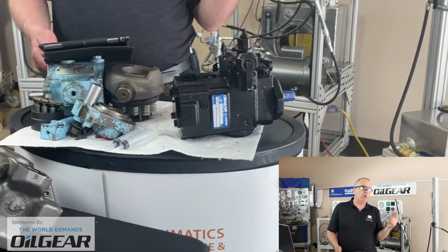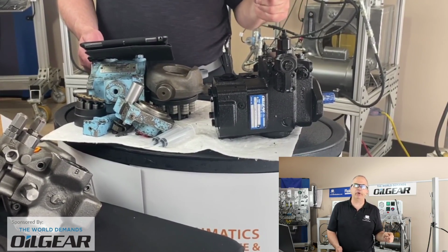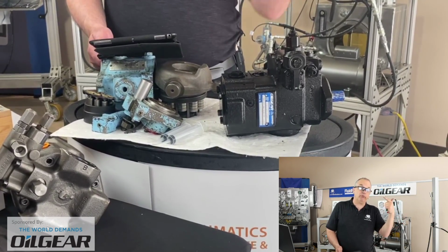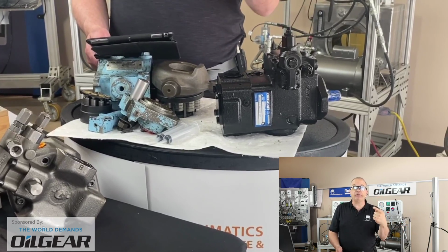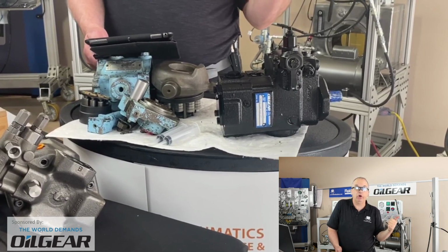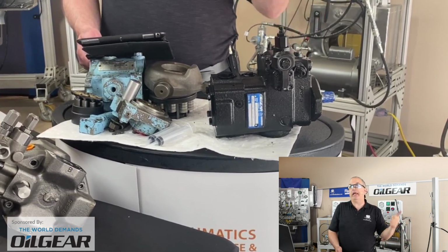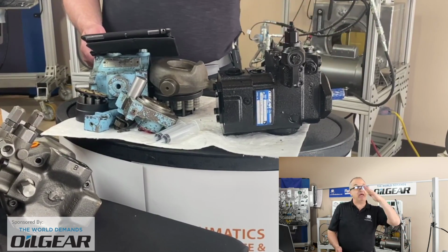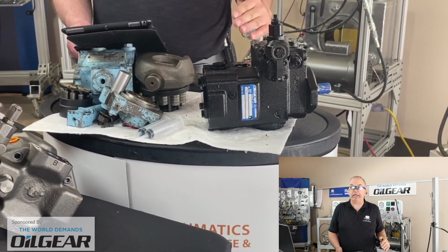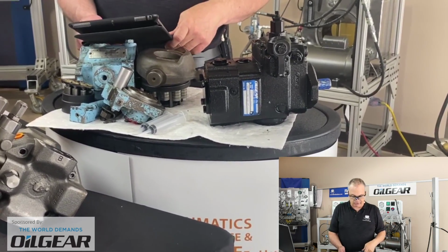Nothing requires more horsepower from your prime mover. Very good point for you to bring that up. Nothing requires more power from your prime mover than pumping at high pressure and full flow. If you get rid of one or the other, you can pump at high flow and low pressure and save a lot of horsepower, or you can pump at high pressure, low flow and save a lot of horsepower. But anytime you have your pump at maximum flow rate and at maximum pressure, that's that diagonal line across the square box in that pump efficiency chart we were looking at, that long diagonal line requiring the most amount of power. Great observation, Andrew, thank you.